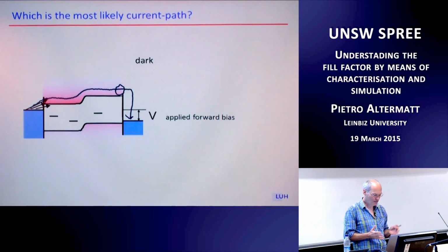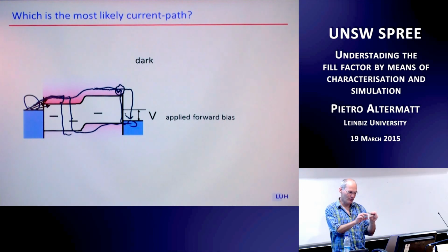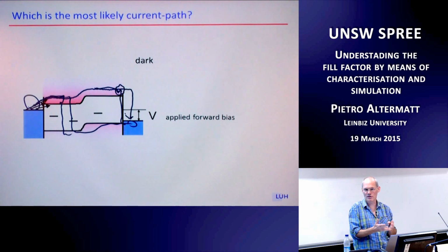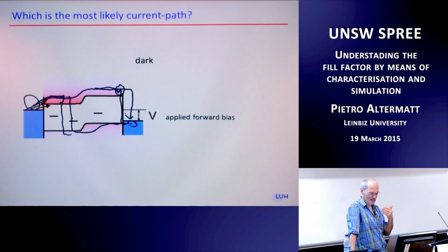So how should the current go? You need to go from here to here. Somewhere the carriers must recombine to get there, even if they recombine at the contact, or they may recombine by Auger or radiative recombination. The exact proportions are what you determine with simulations or an analytical analysis. But you need to be aware that you can't drive a current through a dark diode without recombination.